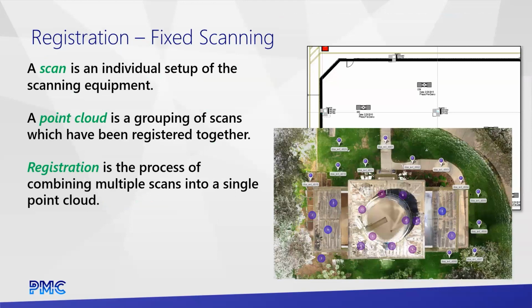So with fixed scanning, like I said, for the very small, you can do on-site registration and upload the data live from the site. If it's a project of any substance, large size, you're not going to be able to do that. So there's going to be some work back in the office. Predominantly, that's going to be registration.